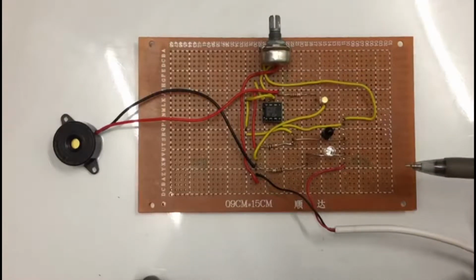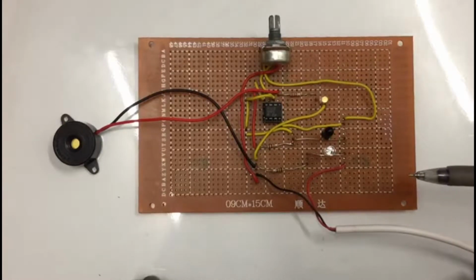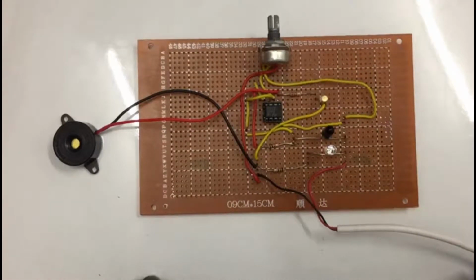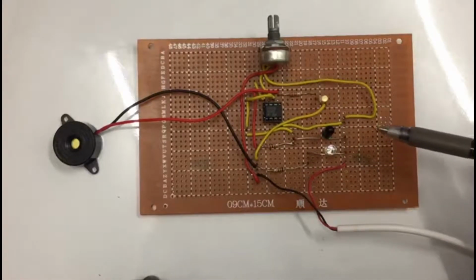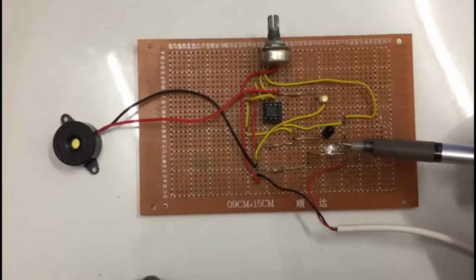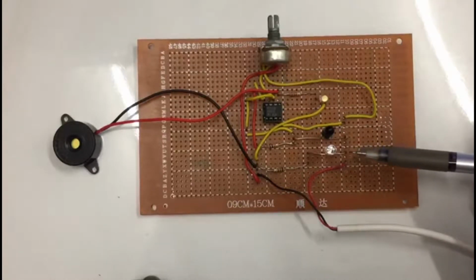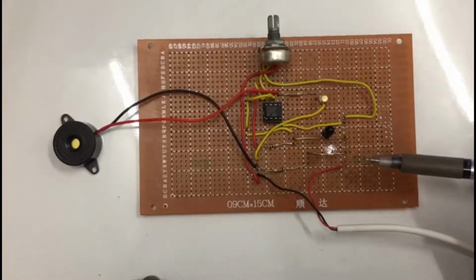A continuous beam of IR rays is emitted by the IR LED. Whenever a reflecting surface, white or an obstacle, comes in front of the receiver photodiode, these rays are reflected back and captured. Whenever an absorbing surface, black or no obstacle, comes in front of the receiver, these rays are absorbed by the surface and thus unable to be captured.